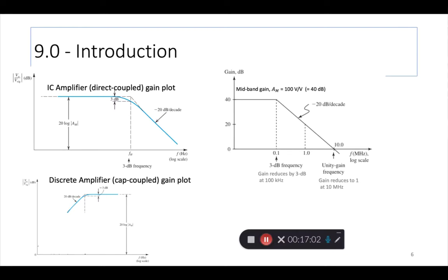So most of the stages, if there is a multiple stage, right? We talked about multi-stage amplifiers in the last chapter. So if you have 3 stages in an IC, they are connected to each other directly. So there really isn't any capacitor on the low end to create problems. So in theory, we can say that the low end frequency response goes all the way to 0 Hertz to DC in an IC amplifier. In a discrete amplifier, that's not possible.